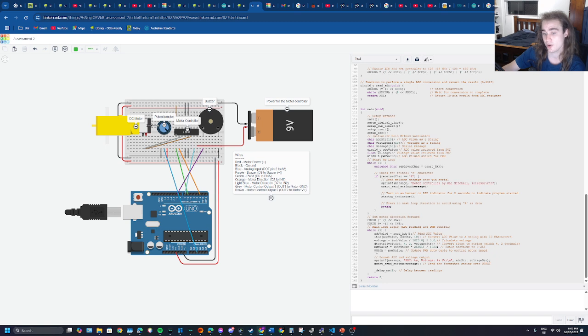Then we set the OCR0A to update the PWM duty cycle. Then we format this message here, ADC percent, voltage percent. So it gives us the message for the ADC value and voltage value, and then it sends it over USART, and then there's just a delay between readings.